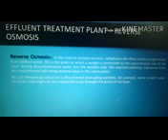The rejected contaminants from the concentrated side are washed away in the reject water. RO can also act as an ultra filter removing particles, for example, some microbe-like forms that might be too large to go through the pores of the membrane.